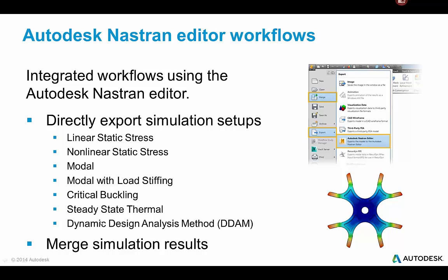Now, for those of you who are not familiar with Nastran at all, you may not really know what you're doing, especially on day one, in terms of looking at these results in a different interface. So you may be reluctant to look at your results in the Nastran editor. So we've also enabled a workflow where you can actually bring those Nastran results into Simulation Mechanical to use our results interface to do additional standard post-processing. So that's pretty straightforward as well.